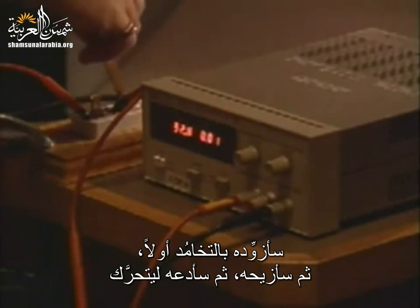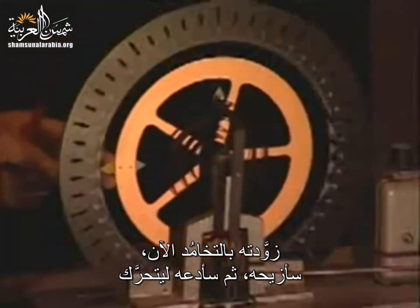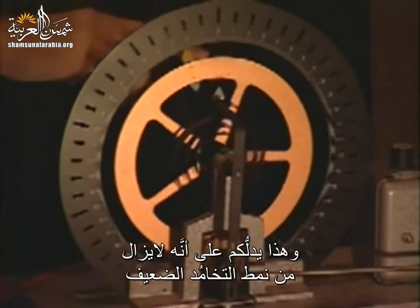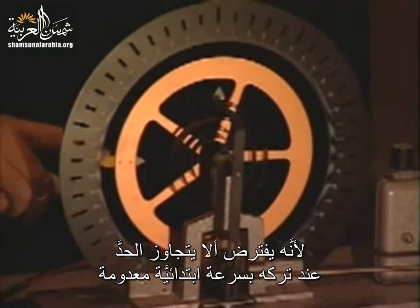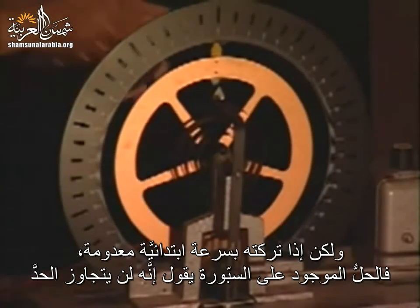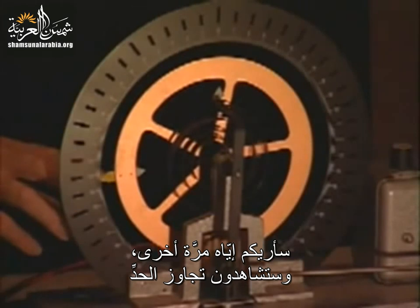So I will first put in the damping, and then I will offset it and let it go. Damping is in now. I will offset it and let it go. 3, 2, 1, 0. You see the overshoot? Just a teeny weeny little. That tells you that it is still underdamped because it's not supposed to overshoot since I release it at 0 speed. Of course, if I give it a push in that direction, of course it will overshoot. That's obvious. But if I do it with 0 speed, that solution that we have on the blackboard dictates that it cannot overshoot. I'll show it once more, and you will see the overshoot.